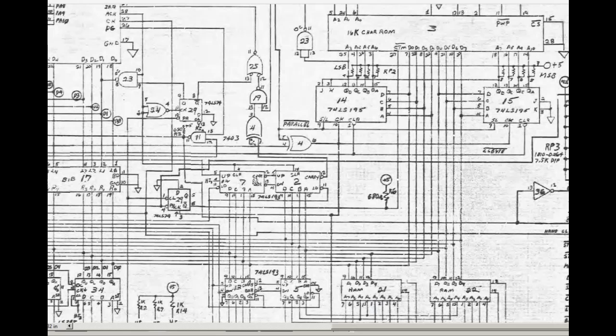When we load the timer for the interrupt, we have to bear that in mind. Now it works out fairly well. This timer increments with each clock pulse, so if the Nano processor outputs a value of 2 because it wants to count 2 cycles, that will be inverted. We'll get FD being fed into the timer, and 2 clock pulses after that we'll get the carry out and we'll get the interrupt, so it works out quite well.